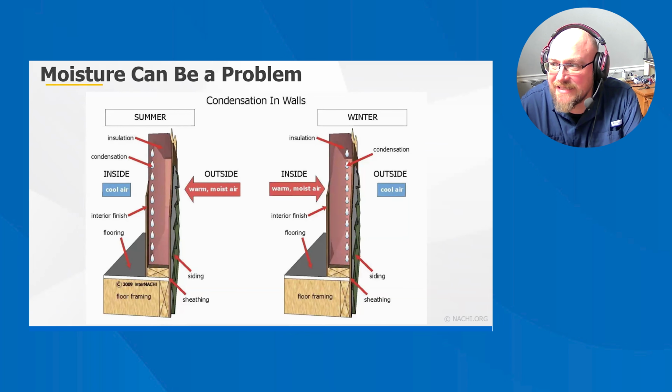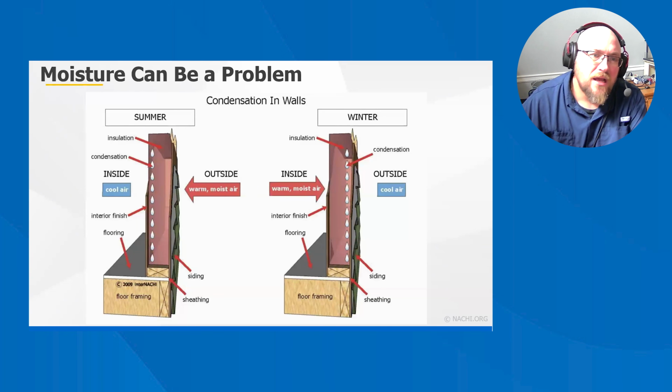When a wall is insulated, the temperature of the space inside that wall is changed. A surface inside that wall, such as the plywood sheathing behind the siding, can become much colder in the wintertime than it was before the wall was insulated. This cold surface could be the place where moisture traveling through the wall could condense and cause trouble. The same situation could happen in an attic.